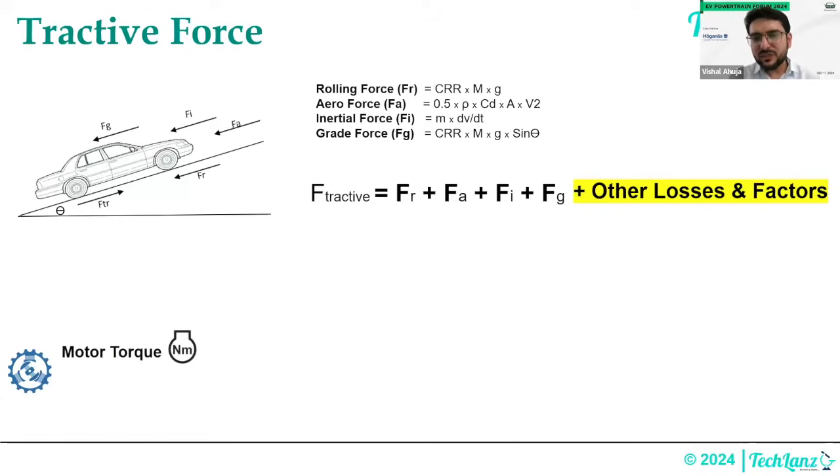Based on when you have the total tractive force requirement, you decide, okay, first you have the gradient level target, right? For a GVW condition I have this much gradient. Then for meeting those gradient requirements as well as my performance requirement, what's my torque level which is required, because torque is nothing but force into radius, right? You know my tire radius, you know the force, you get the torque very straightforwardly.